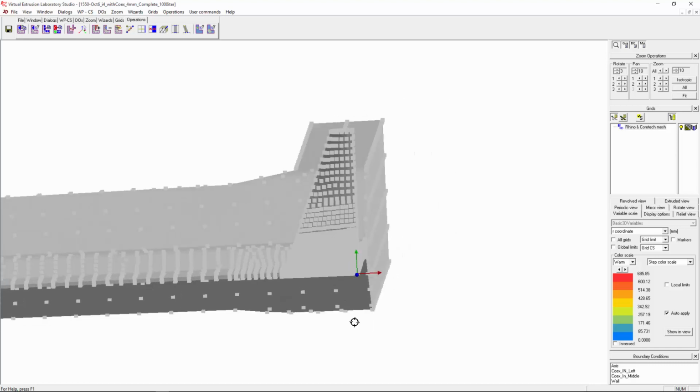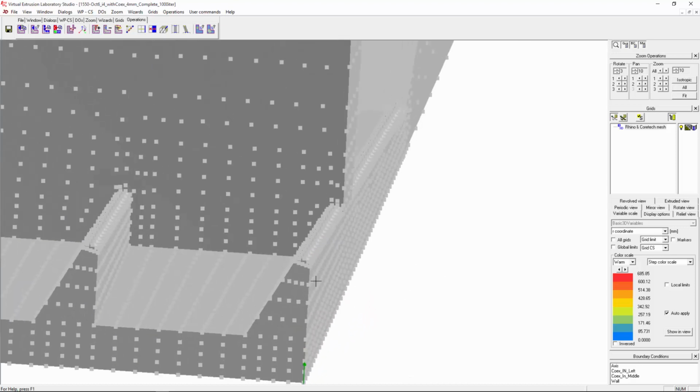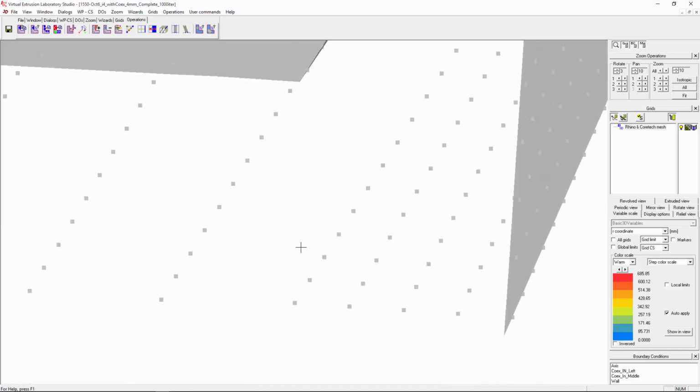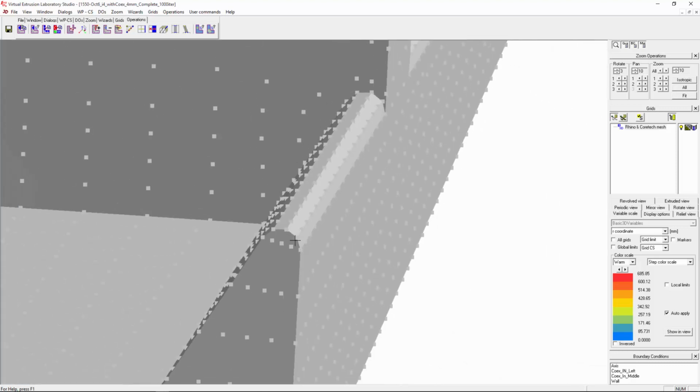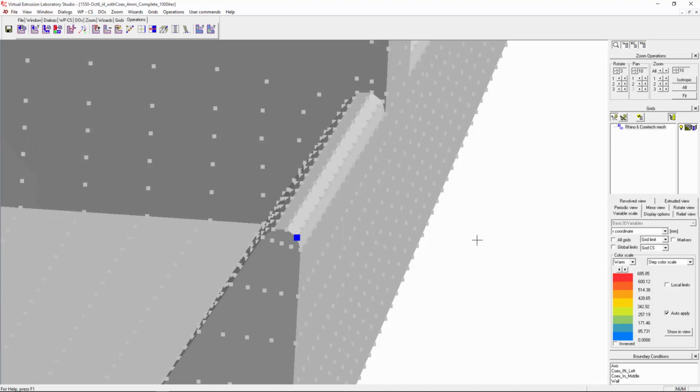Now, how to correct this? First, of course, we should write some automatic fix, but I always check what is the nearest point, and I can expect that this row of points is probably the nearest ones. Let's see what is the coordinate. This one is only x minus 0.03, right? So I'm sure that probably there is not any point nearer than 0.01 to the axis. If it's nearer than 0.01, that's probably supposed to be an axis.